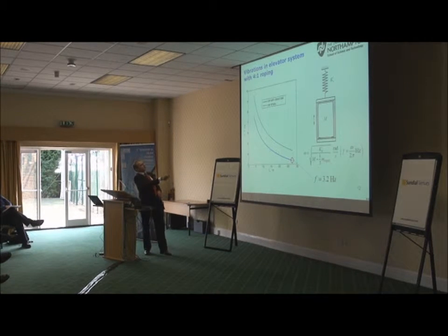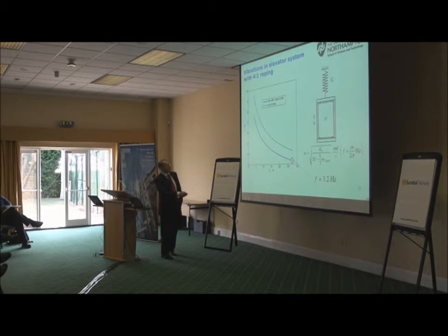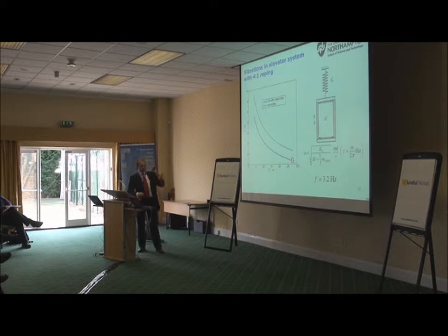The first curve is the empty car, dashed; solid is with rated load. When the length of the ropes changes, the frequency changes because it affects the stiffness.